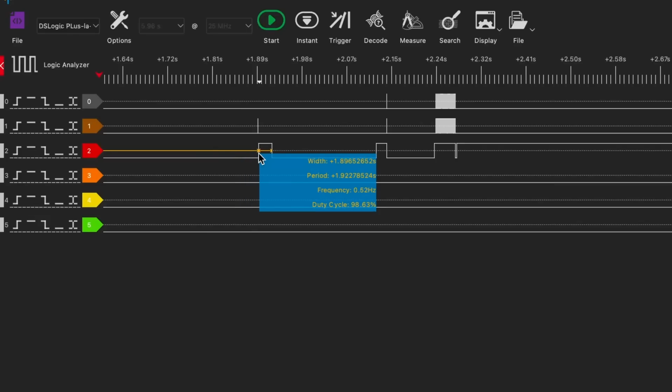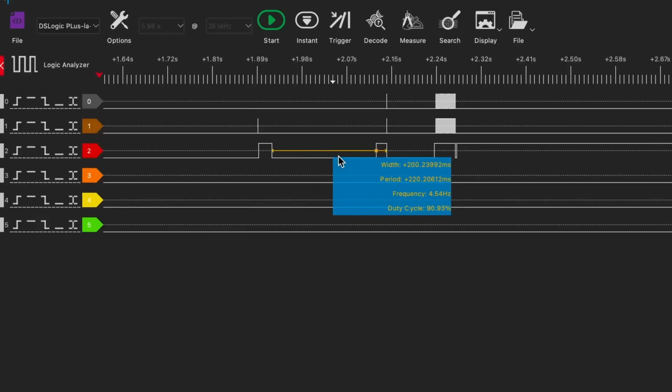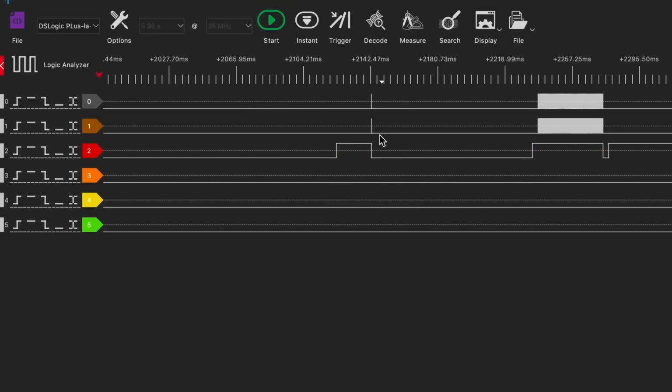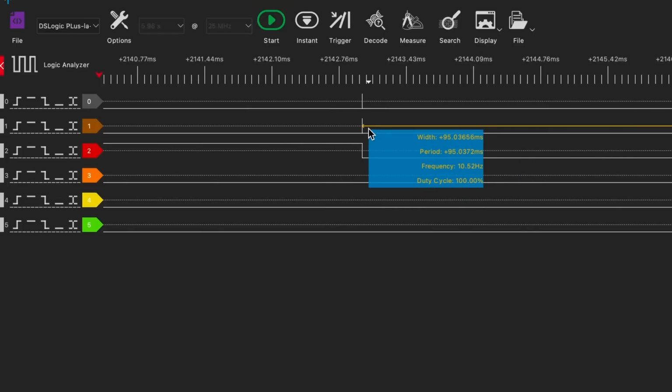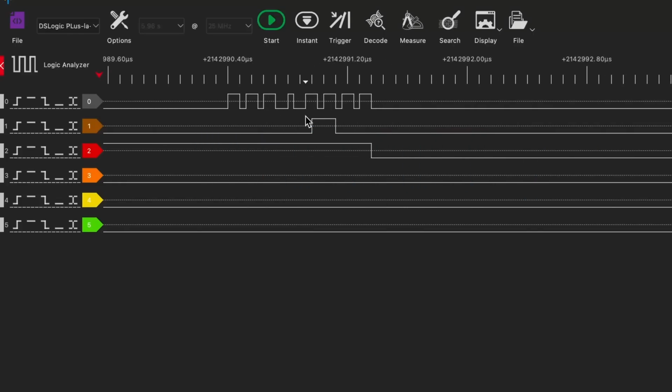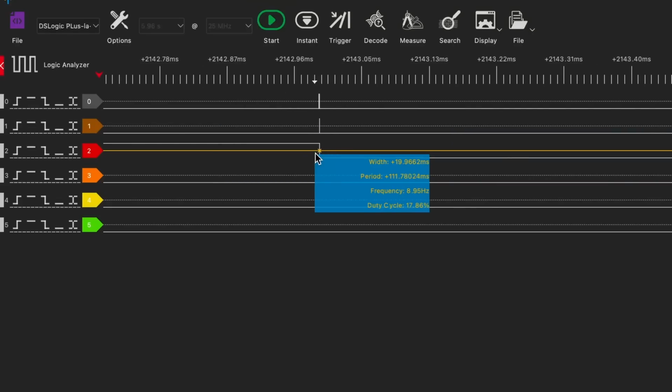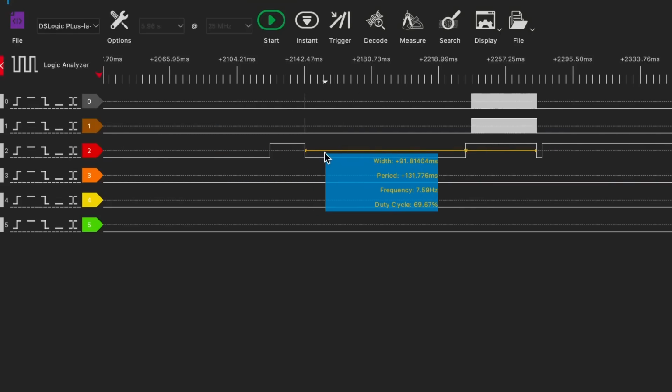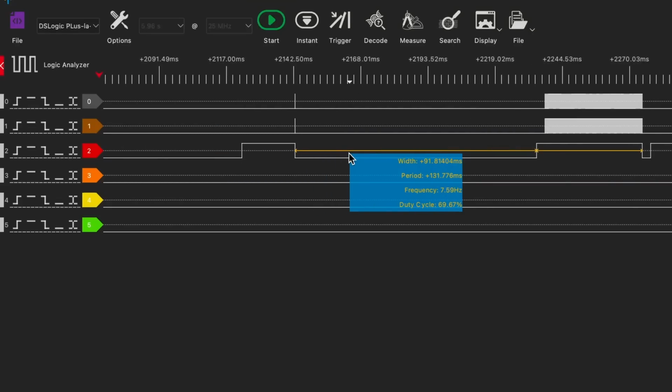We can actually see, yes. The busy line first comes high, meaning it's not busy, then goes low again. That means the microcontroller has sent a reset pulse, so it's been under reset. Then it becomes high again, and we go into here. It's 0x04. Actually, we send the power on sequence, and yes, it does do the power on, and takes about 90 milliseconds to power on.